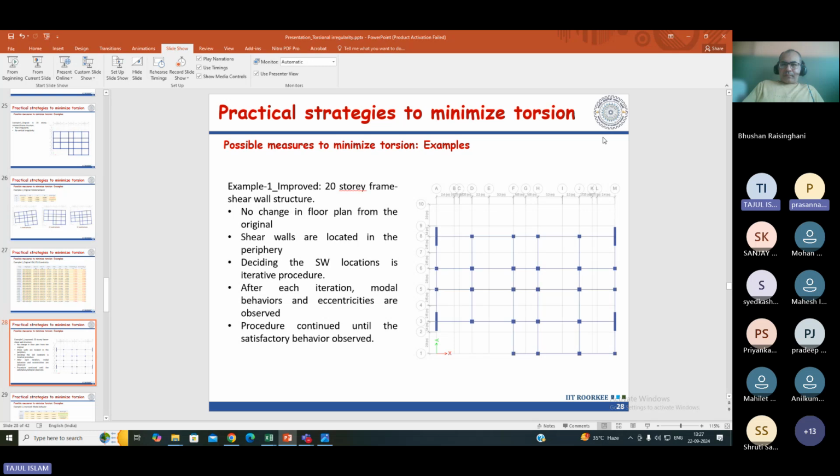No, torsion will be taken by the software automatically. Why are you worried about this? For wall design and column design, it will not take it. For beams, you have an option. For beams, as per the IS 456 procedure, it will design. But coming to columns and walls, it will not take this additional torsion force while designing the reinforcement. This will be ignored simply.